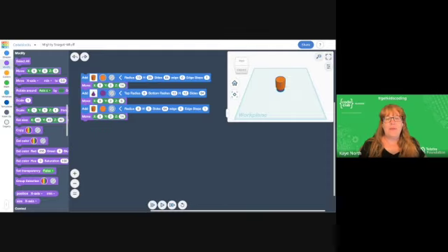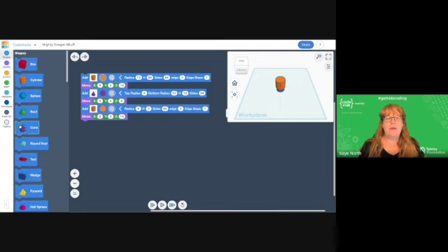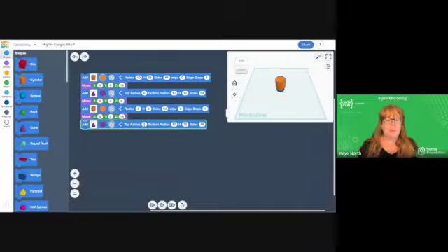Now that we've got our bottom cone, we've got our cylinder that's going to join in the middle, we need a cone to go on the top. Once again, acknowledging that it's creating a hole in the middle of our fidget spinner. This time our top radius is going to be 10. Our bottom radius is going to be 6.